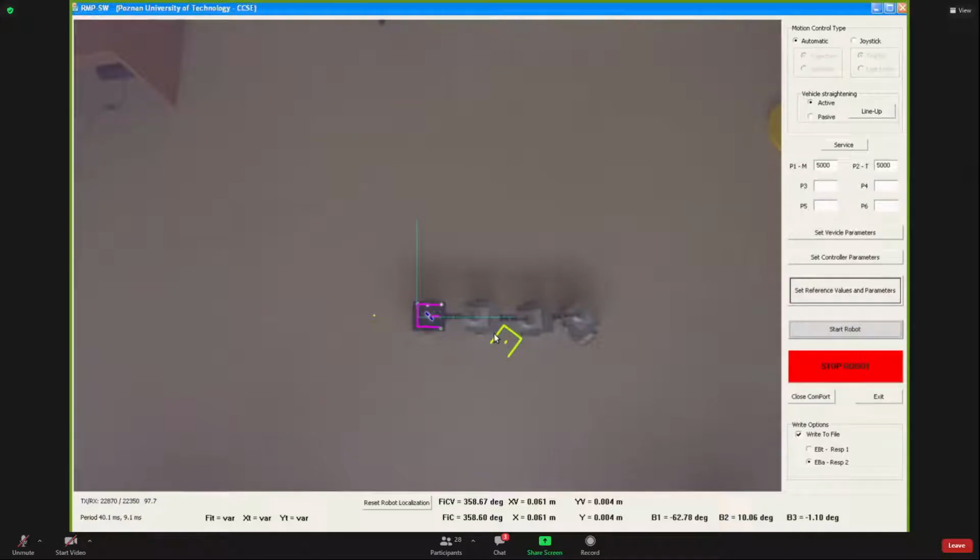Here is the situation that the box you are trying to park is moving. So simply you would like to follow a trajectory. So here you will observe how the trajectory evolves along the time, and we would like to catch up this element with our trailer and just follow it exactly like it is. So one can say that now at the initial condition, we have some initial error in the sense that the trailer is not at the place we would like it to be. And after some time, this error will get smaller, hopefully will get to 0, and then we will follow exactly the point we would like to follow.